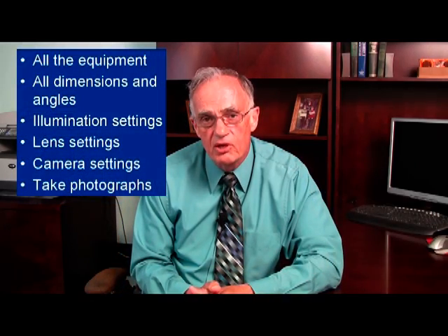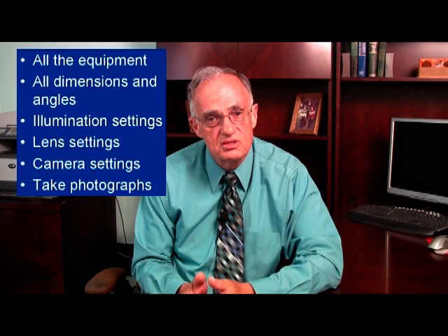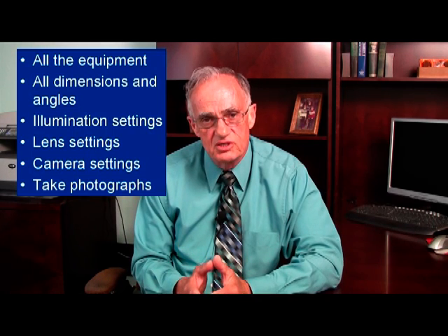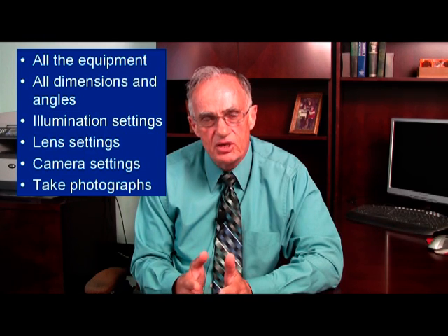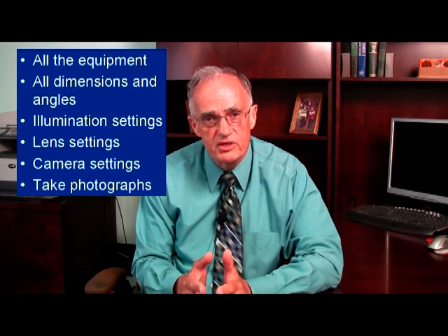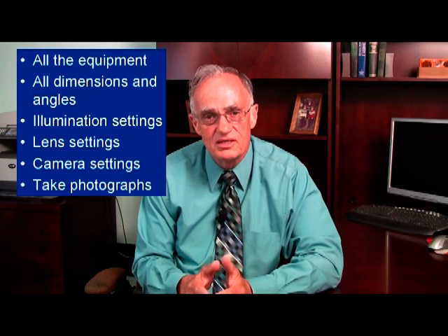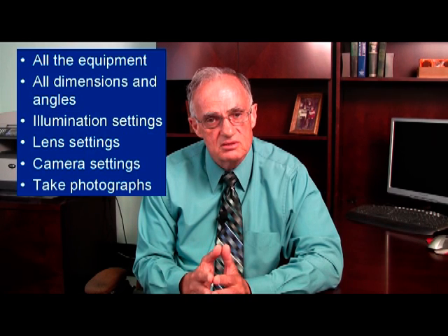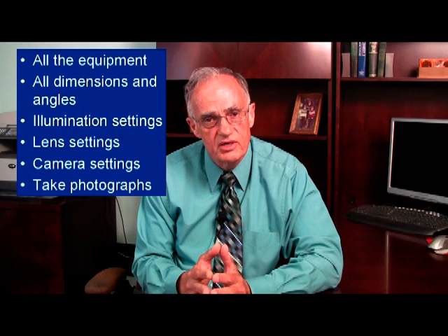Before you begin your benchmarking measurements, make sure you record all of the components, dimensions, and settings of your vision system. Now, if this is a well-documented vision system, your bill of materials will list all of the components, and your mechanical drawings should show all of the critical dimensions. However, if this is a laboratory system, you will have to make a list of every component, make, model, and option, and measure and record all of the dimensions, including angles.